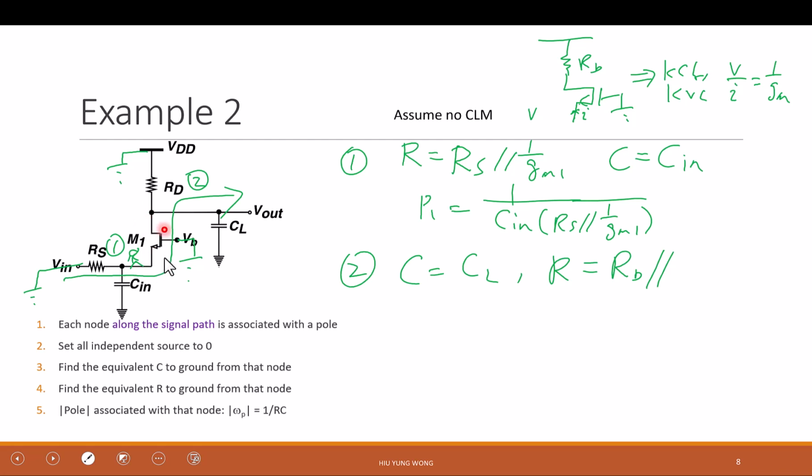You may forget the equation, but it is not R0 plus RS, right? It is R0 times (1 plus Gm RS) plus RS. It's okay that you forgot the equation, but you definitely need to alert yourself: oh, this is not just a common source. So you need to keep practicing this.